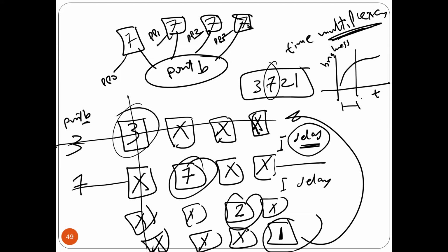So you have to keep it for a certain time. Okay, 1 millisecond, 2 milliseconds, you can try and see. So what I'm telling you, after you write your program, if you find that the 7-segment LEDs are dim, that means the delay is too short. You have to make the delay bigger.